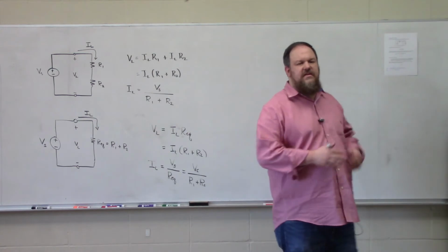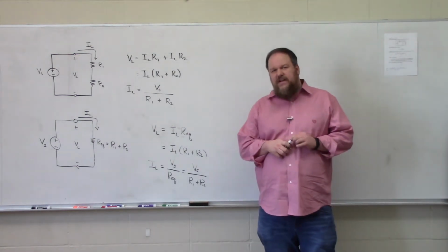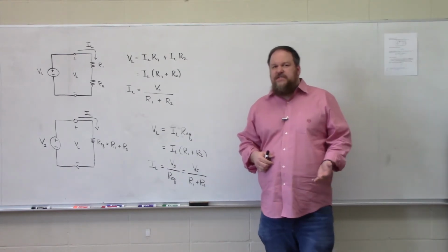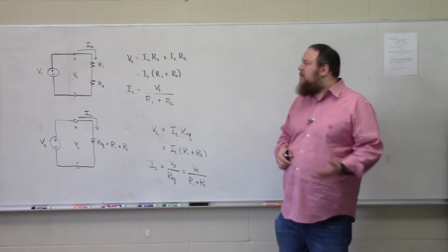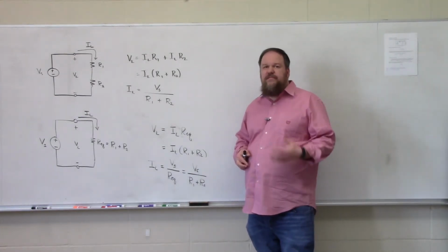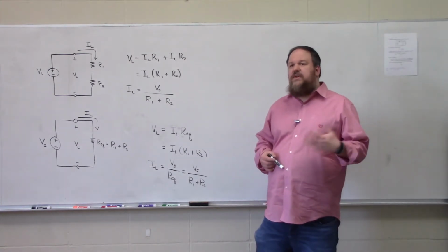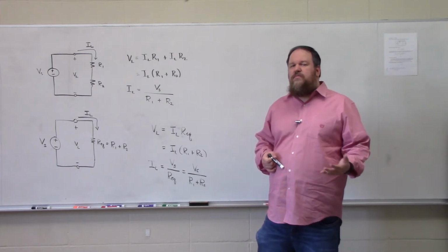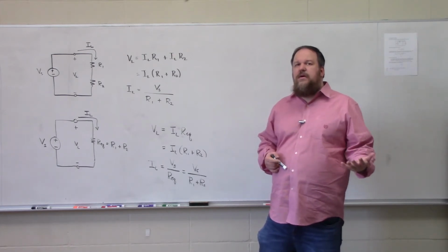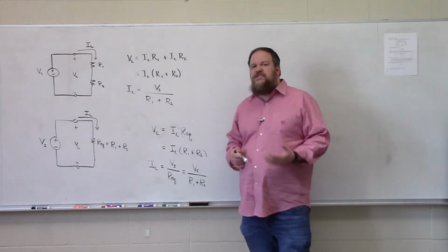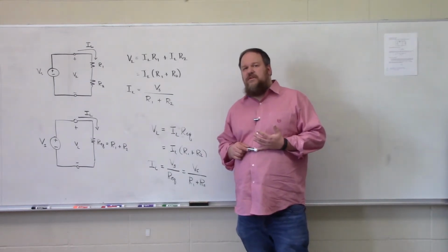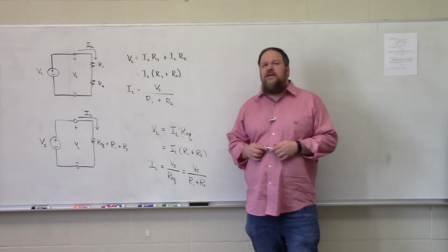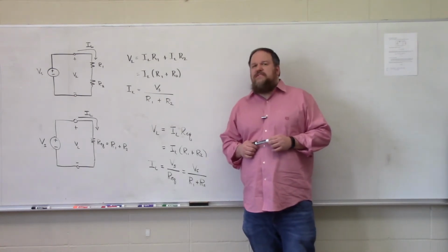And this is what we visited when we talked about resistor combination techniques. We could work a similar example with parallel resistors, but we already know what the result of that is going to be. We could work an example where, looking from the perspective of the resistor with multiple voltage sources, we could develop the rules for source combination of voltage sources. Or from the point of a resistor, we could look at a network that had current sources in parallel and develop relationships in order to combine those parallel current sources into a single equivalent current source, which we've all done before.